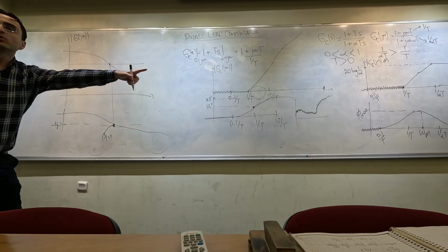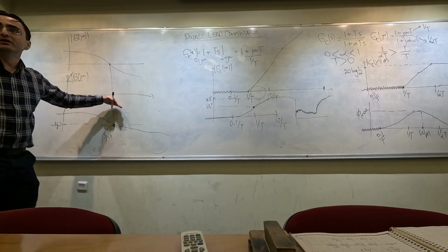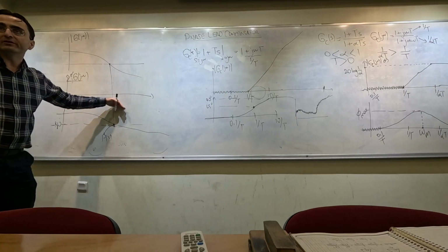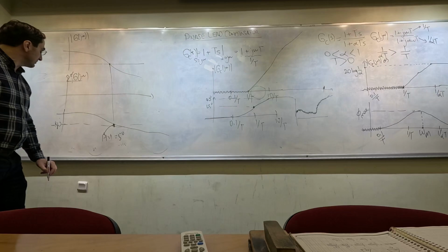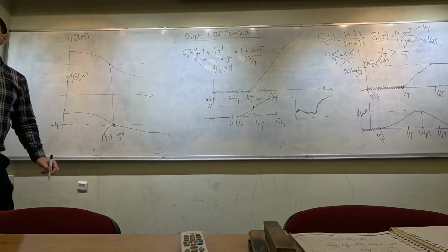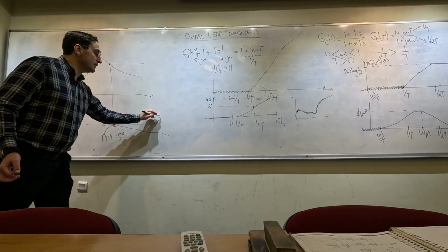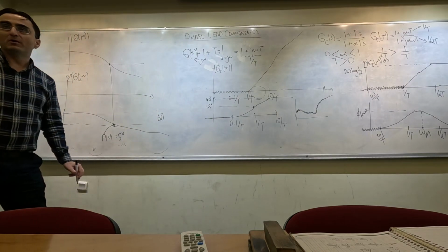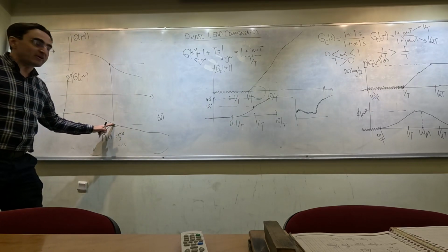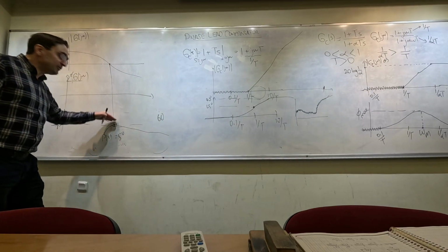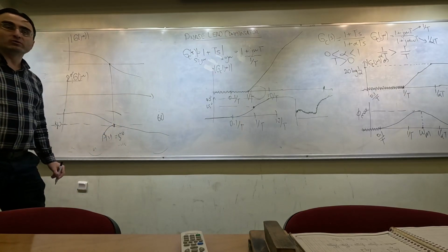That is why I am going to use that compensator to increase my phase margin to a required position. For example, this phase margin is approximately 5 degrees, but in my requirements I need 60 degrees phase margin. This means that I need to increase this phase by 55 to a value somewhere here.